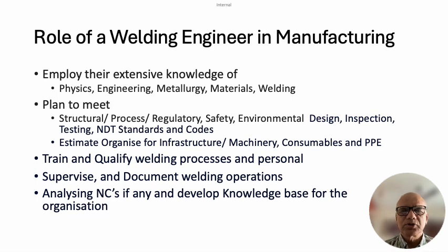and accordingly additional welding procedures if required are qualified, and then we need to qualify the personnel depending upon the type of joint, depending upon the position in which we expect that particular joint or the number of joints in that equipment are going to come, the environment in which he is going to weld it, the machines on which he is going to operate. So welders and welding operators will get qualified. Then the role of a welding engineer changes.